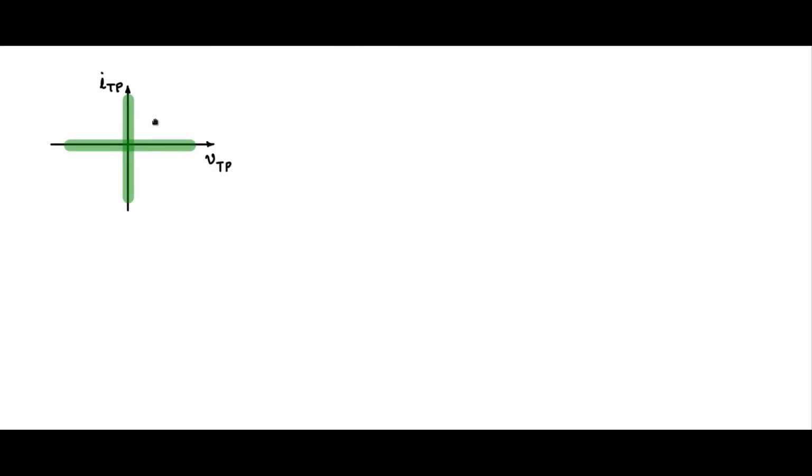We see here the static characteristic of an ideal switch. During the on time, we see that the ideal switch is capable of supporting both positive currents and negative currents to flow through it, throw to pole and pole to throw. And while the switch is off, it can support a positive voltage across the device and also negative voltage across the device.